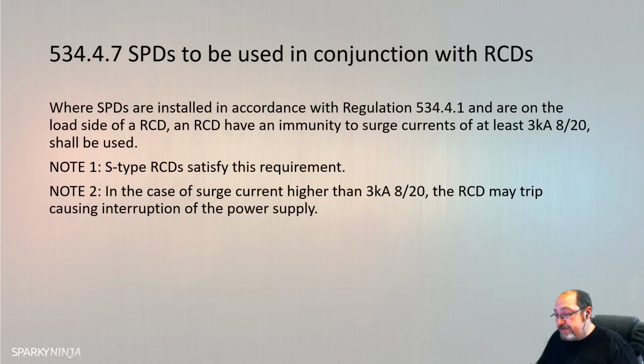There's a bit on the critical length of the conductors for the SPDs as well. We have maximum lengths there. With regards to connecting an SPD, we have to have critical lengths because the size of the conductors doesn't really affect it. It's to do with the actual inductive effect of that value of voltage that's going to be there. So we have to minimize the length as short as practicable. There are examples of the different connection types there, no difference to the previous regulations, really.